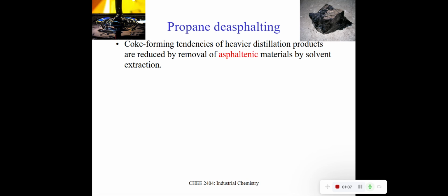Now this propane deasphalting depends on the solubility of hydrocarbon in propane, right? The vacuum residue is fed in such a way that it flows counter current in the deasphalting tower.